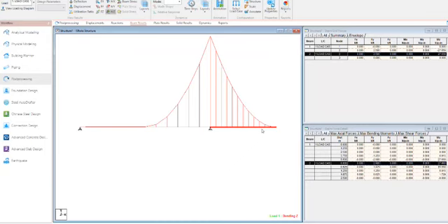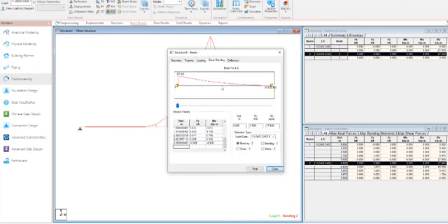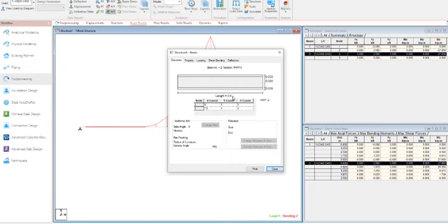So this is 2.5 into 1 into 2.5 kilonewton into 2.5 divided by 2, right? So this moment we need to calculate, right? The bending moment, how we can calculate? This is the uniform distributed load. Load into distance, right? Load is how much loading, 1 kilonewton per meter, and what is the distance of this member? 2.5 meter.